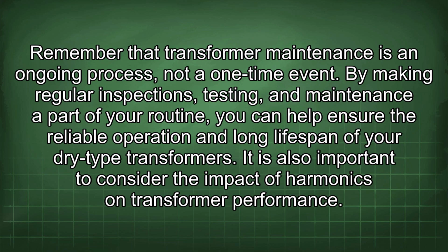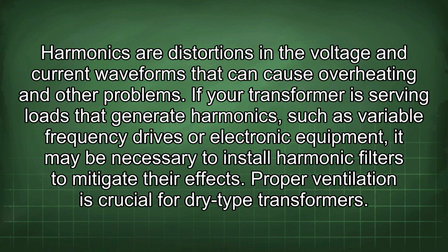It is also important to consider the impact of harmonics on transformer performance. Harmonics are distortions in the voltage and current waveforms that can cause overheating and other problems. If your transformer is serving loads that generate harmonics, such as variable frequency drives or electronic equipment, it may be necessary to install harmonic filters to mitigate their effects.